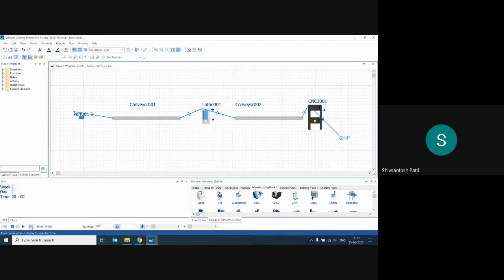Batch is for when you want to run the model in a very fast way. So that's the batch option. Here your main ones to use are the green button, this blue button, and this begin button. Begin means reset and rerun the simulation. Blue is for stopping.